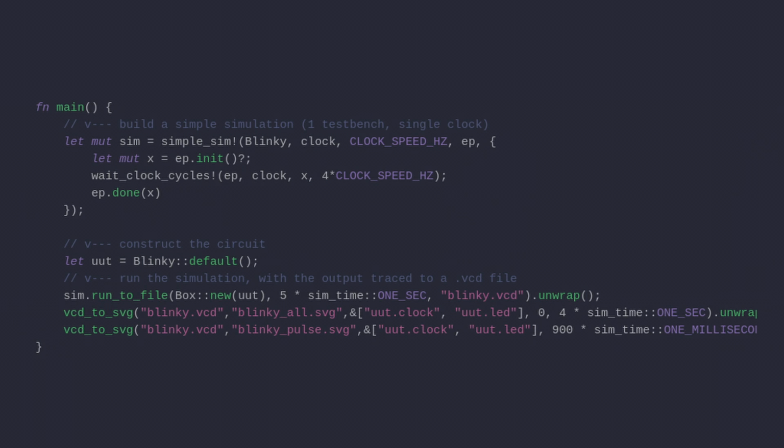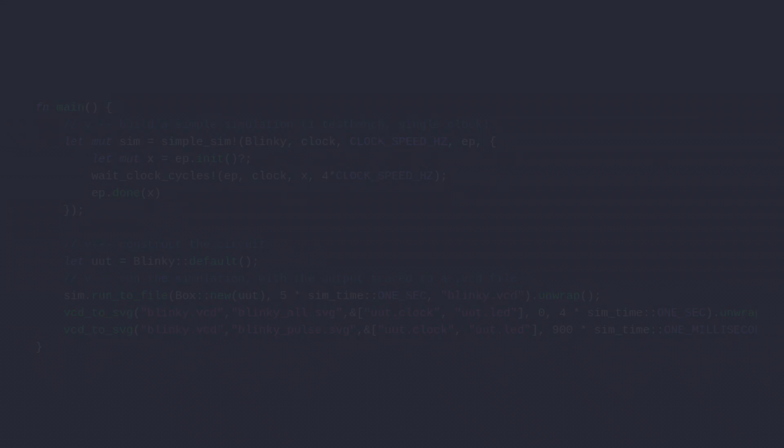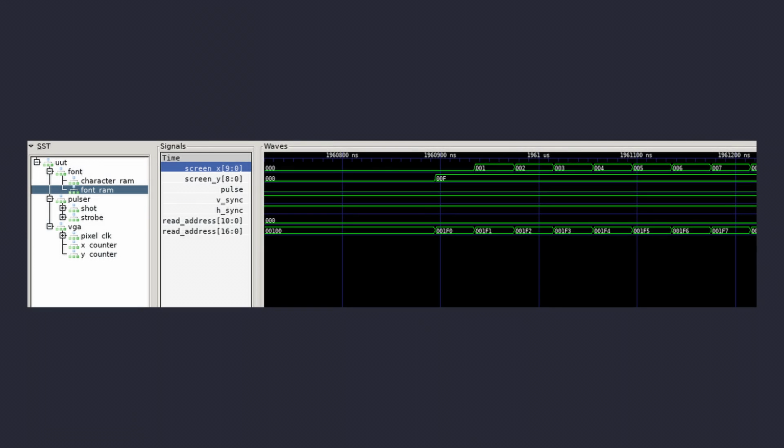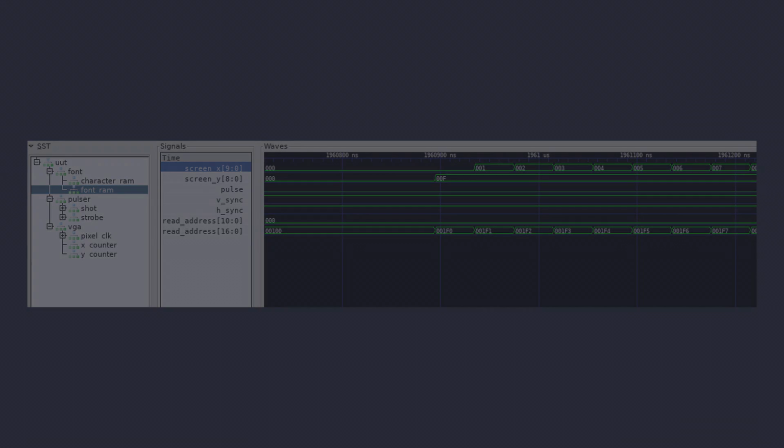Then they call a simulation macro, which we can explore in a future video, but basically I just want this output VCD file. These VCD files can be viewed in the viewer of your choice, but they can get rather big if you simulate for a long time. I can't go into all of the details here, but you can see the waveforms of various signals in your designs, and you can verify that everything is working exactly how you'd expect before you flash it to your hardware.